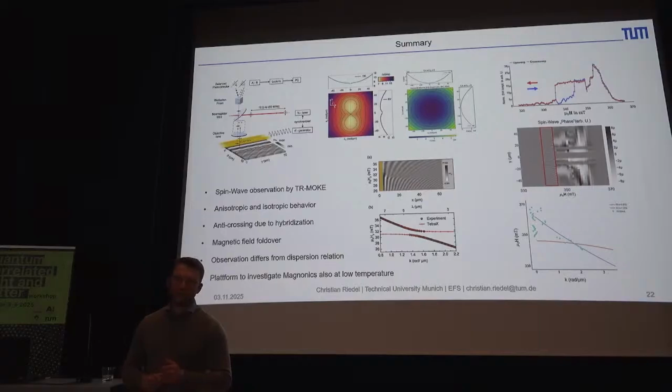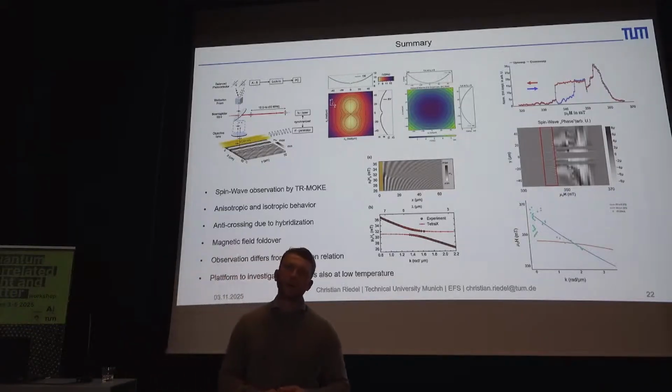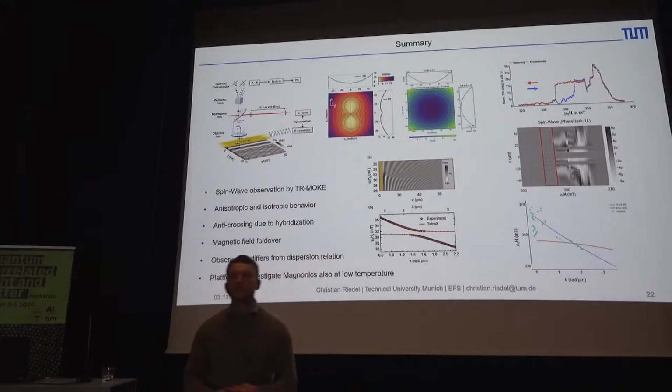Practically, I think the impedance match would be very horrible, meaning that the thinner you get, the less RF power you get through it anymore. But if you use an amplifier and so on, then yes, people are actually doing this. If they do short spin waves in the exchange regime, where the wavelength gets shorter and shorter, then they are also doing smaller antennas, but then you have to go to scanning transmission X-ray microscopy, for example, to get a higher spatial resolution.